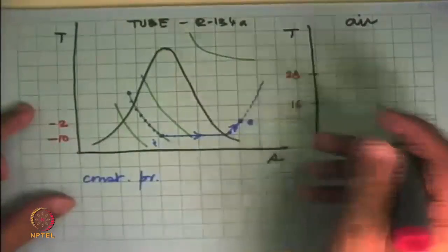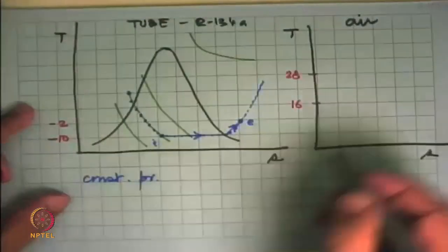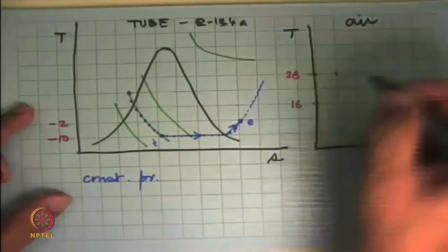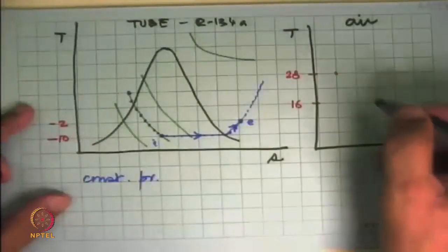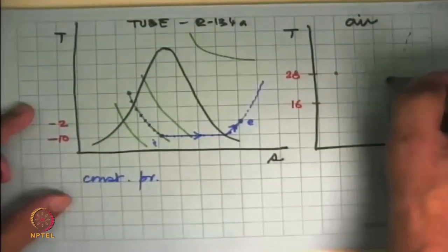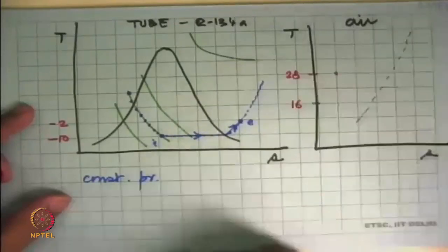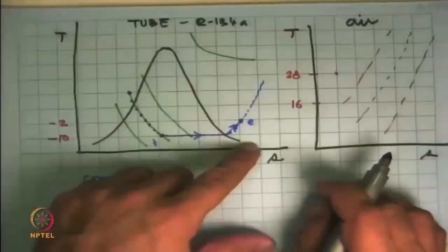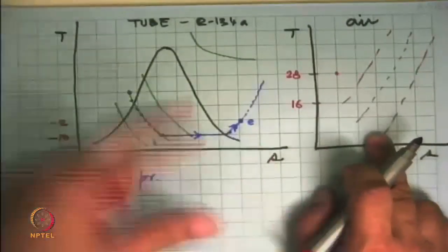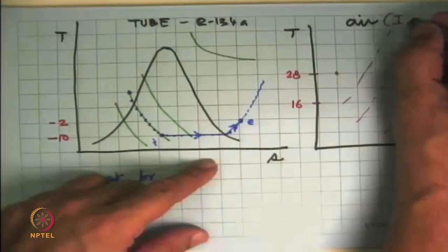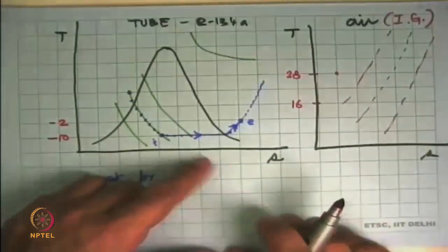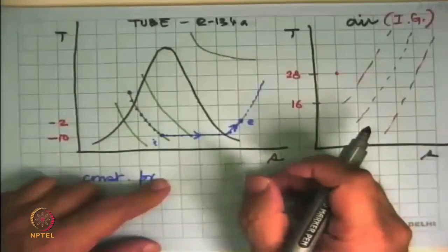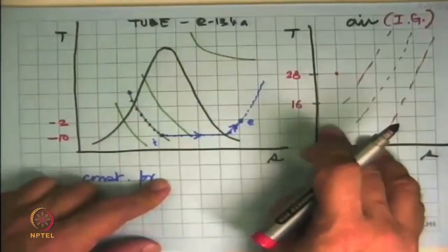And we know that as the air goes through it, its temperature decreases. So it started off having a temperature over there, and pressure is again constant. So we have to take a constant pressure line on this. In this case, the constant pressure lines look like that on the T-s diagram. The dome does not have to be shown because this is not a vapor state. We are implicitly saying and assuming that air is an ideal gas. And for an ideal gas, the dome is not to be shown, but we show the constant pressure lines and say, now where is the inlet state?